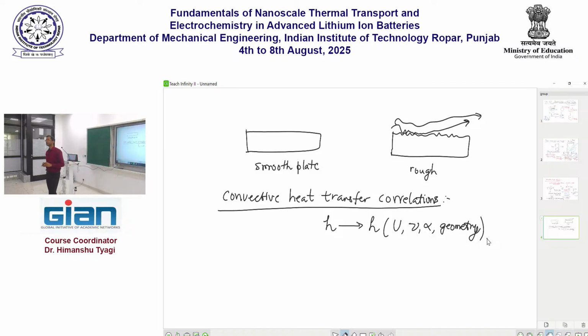So yes, sorry. Good question. If the change in pressure causes a change in velocity, then yes. But if the velocity remains the same and you change the pressure, then that by itself will not change anything. Okay? The pressure can also change the properties of the fluid. So it can have multiple effects on each of these things that ultimately affects the heat transfer coefficient. But Boyle's law cannot directly do that. Boyle's law can predict that. Boyle's law, PV equals nRT, exactly, yes.